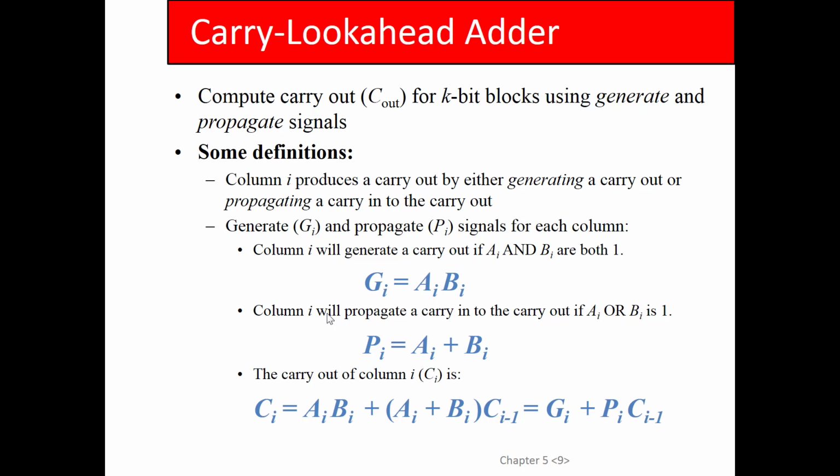Now, in this case, it's not that much faster because it's only 4 bits. With a ripple carry, I had to go through 6 gate delays to get my carry in on this guy. With this carry look ahead, I had to go through 1 gate delay to get generate and propagate plus another 2 to get carry in. So I'm looking at 6 gate delays versus 3, ripple carry versus carry look ahead. So I halved my time.